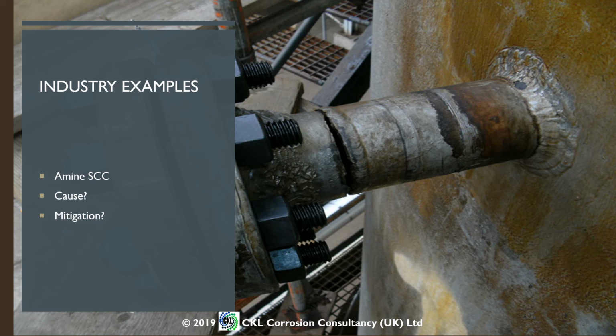So we had this issue, and then we had to work out an engineering solution to try to resolve the problems, with advanced welding techniques using nickel-based weld consumables to help eliminate the cracking problem. Okay.